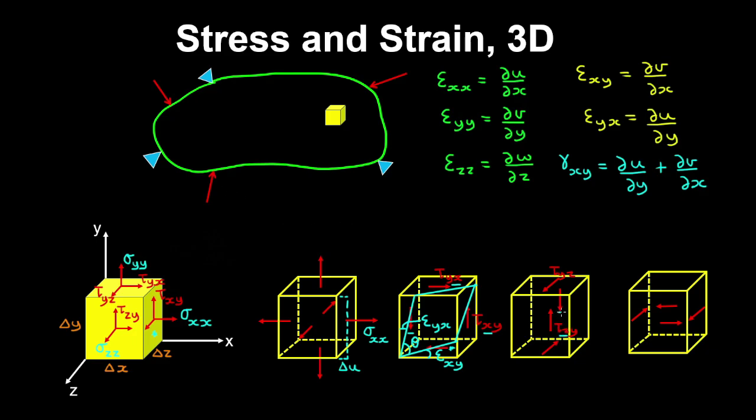So this shear stress couple is going to cause the following distortion, which is the shear strain epsilon zy, and then this shear stress couple is going to cause the following distortion in the yz plane. So this is epsilon yz. So pause the video and try to write these strains as we did for the xy plane while we continue.